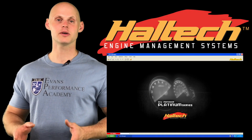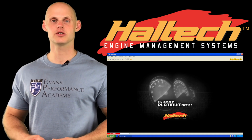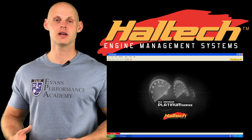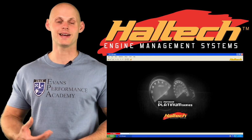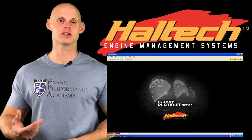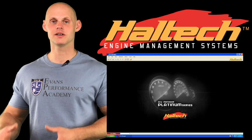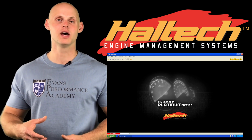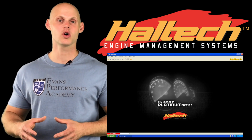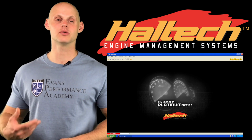Let's get this video started by talking about our acceleration enrichment feature we're going to find in our ECU Manager software. Now, Haltech is going to be calling their acceleration enrichment this Transient Throttle Enhance. So it's going to be the same thing as what we learned in EFI Basics and EFI Advanced when we talked about the acceleration enrichment feature. It's just going to be called something differently. So the terminology is going to differ a bit from other standalone systems like AEM or maybe Motec. It's going to be called something different, but it's going to work the same way.